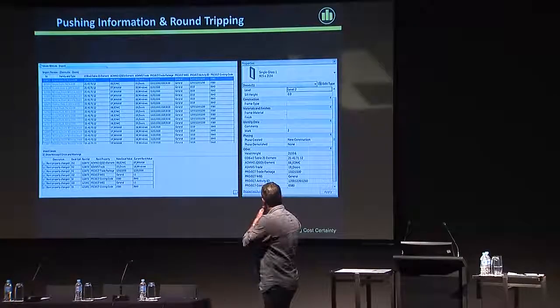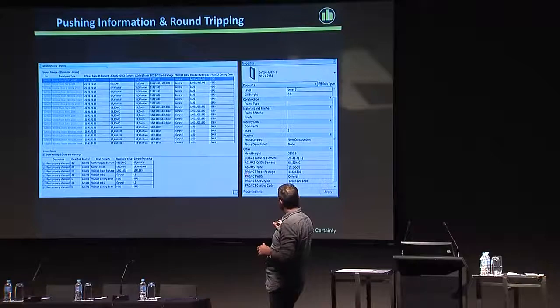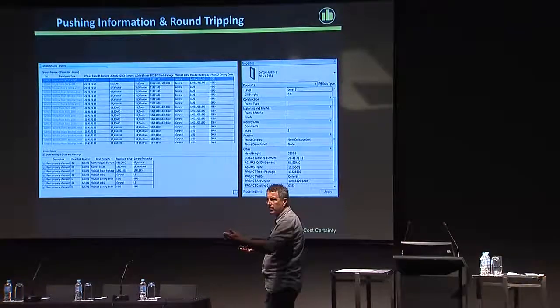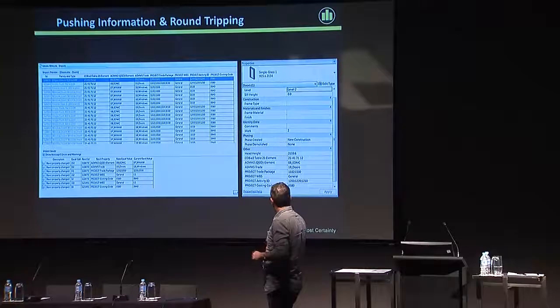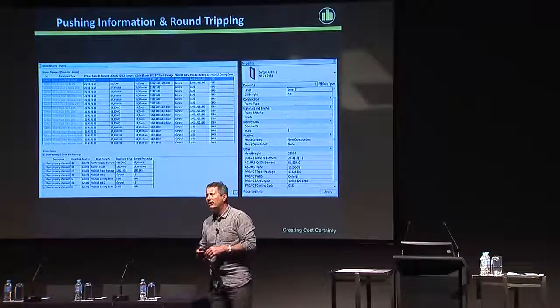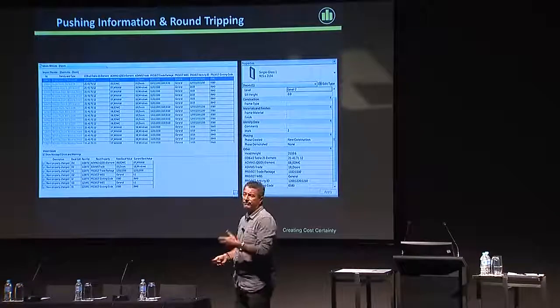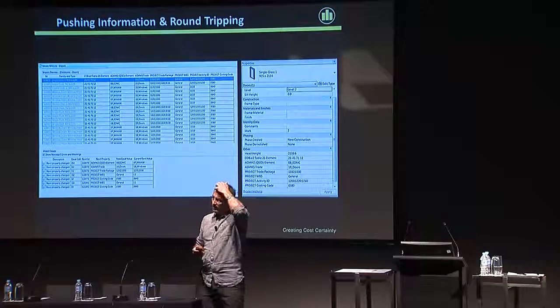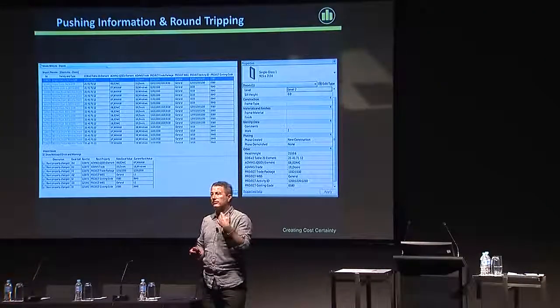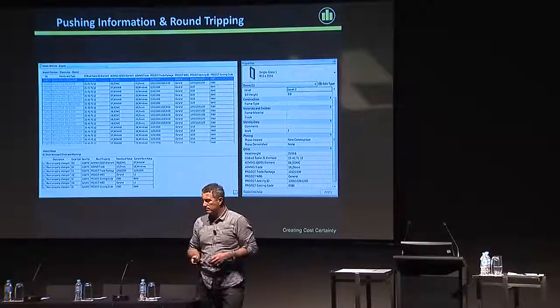The types of information that we use, this is looking at some property sets. The main ones we get involved in here are trade package codes, which are useful for subcontractors to filter a model by trade package. We can also look at activity codes, costing codes, all that type of thing. Where we work for subcontractors, we put general ledger codes in and things like that. We use an add-in called BIM Link, which is a fantastic thing. It's been around for a number of years now, but it allows us to create instance parameters across a whole family. So you're not having to deal with one-off pieces of data, you can deal with this in mass.